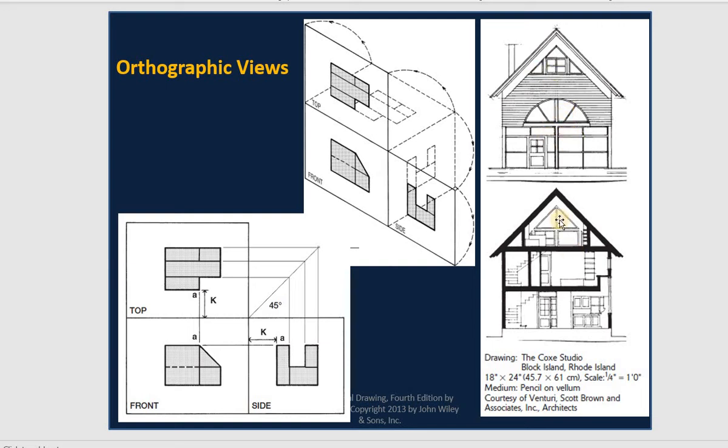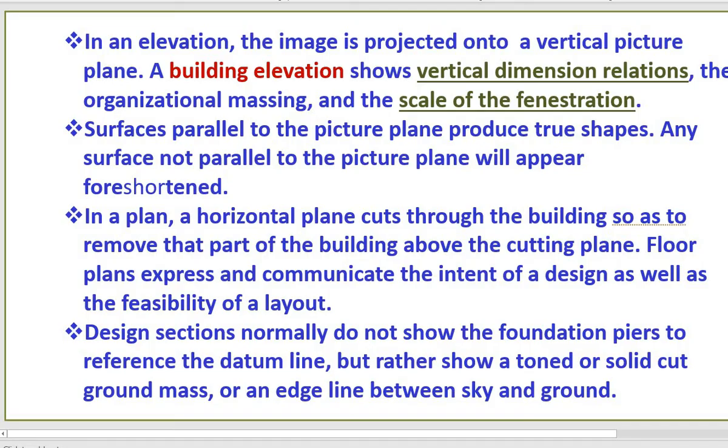elevation. So now you see exactly similar to elevation. That means you see the height of the building, but you have more structure of the building. For example, you see the stairs section cut, you see the column, you see the wall, some detail of the window, and you see up the ceiling height, the ceiling and the height of the slab between them, and you see the roof structure, and everything you can see more detail of the structure. You call that the section. So that's the difference between elevation and the section.